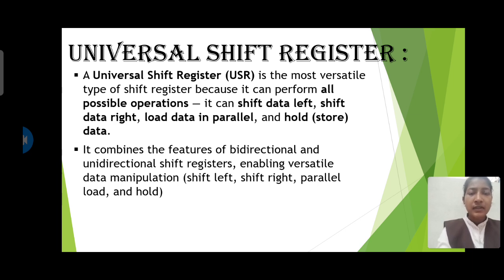And the next point is it combines the features of bidirectional and unidirectional shift registers, and it enables versatile data manipulation. That means shift left, shift right, parallel load and hold or store.